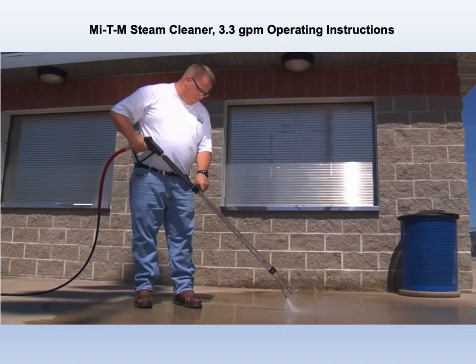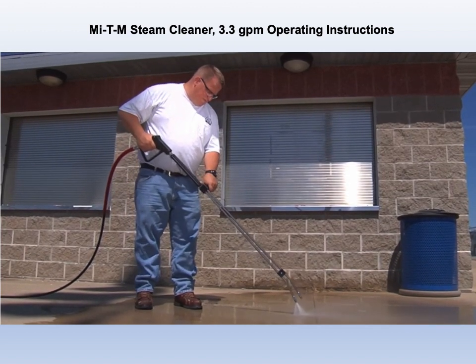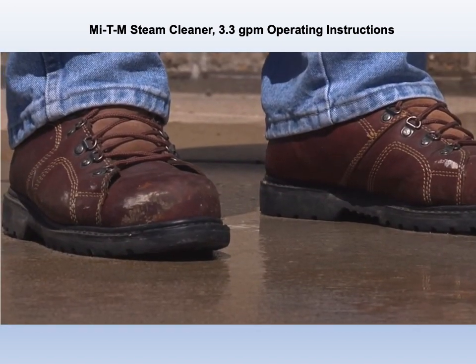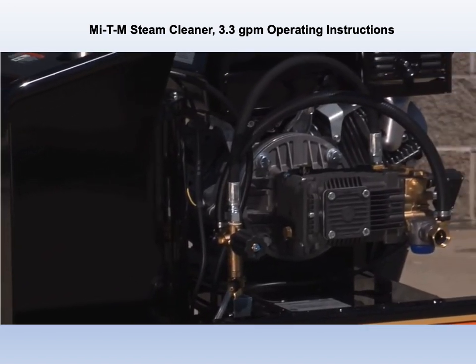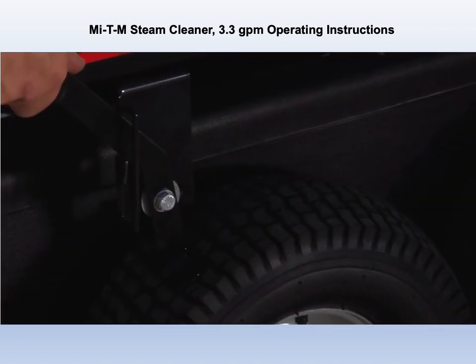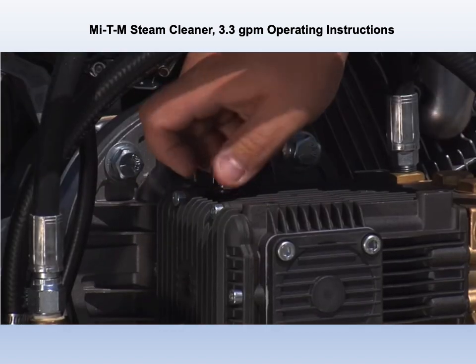As with all gas-powered pressure washers, always operate them in a well-ventilated area. Always wear safety goggles and closed-toe shoes, and protect yourself from the possibility of direct spray. Do not come in contact with the engine, muffler, or heat exchanger. Make sure the pressure washer is on a flat surface and the brake is locked. Check the pump oil and engine oil level before each use.